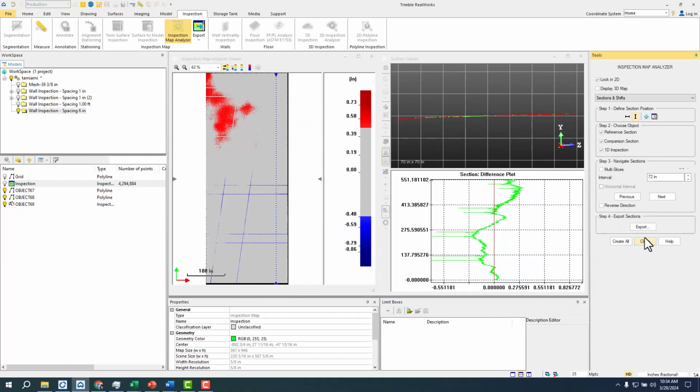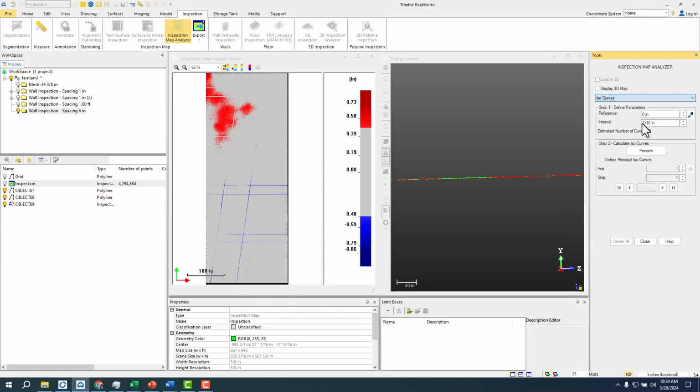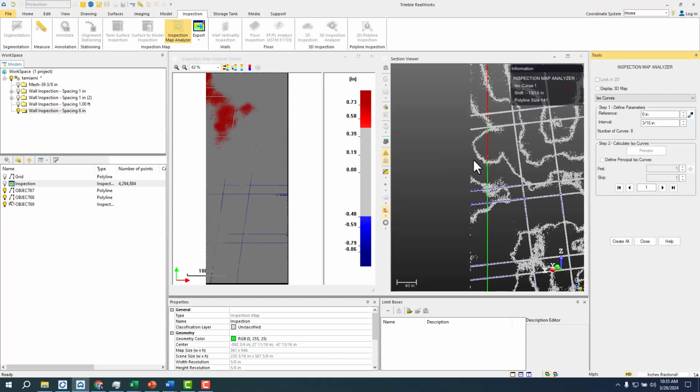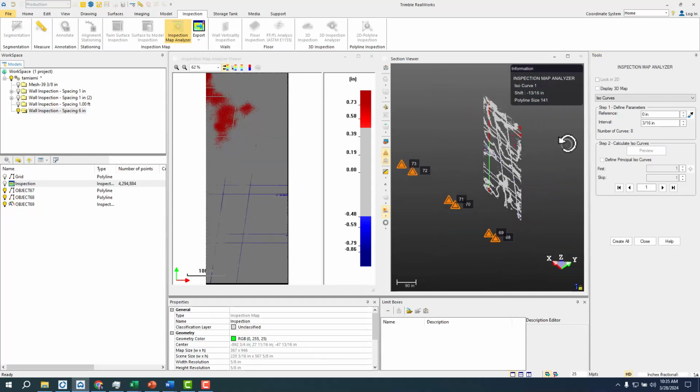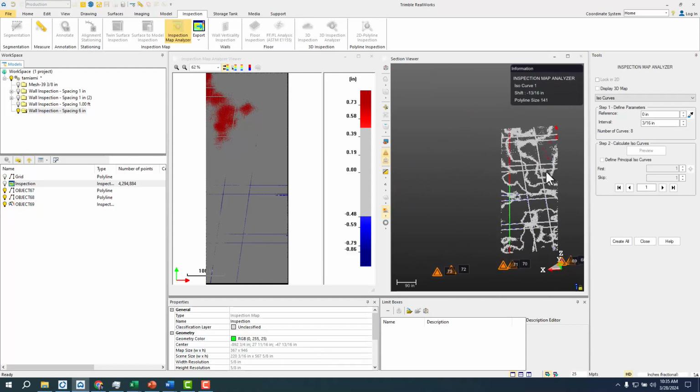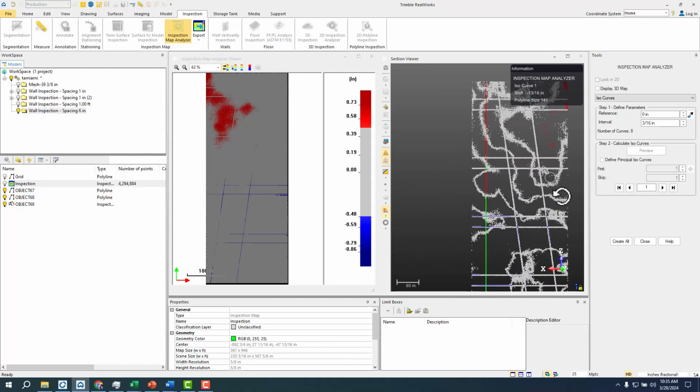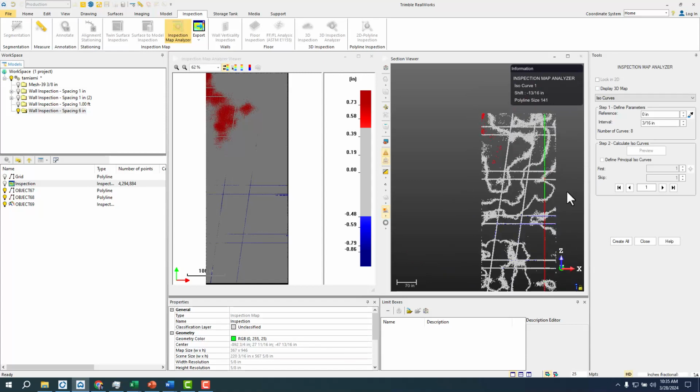And the other thing I can do, rather than just doing the vertical wall analysis, is do a contouring map, which can also be pretty nice because it's a little bit easier to interpret what the deliverable is there. Those section cuts are going to give me very precise differencing. Contouring will as well too, but this is sometimes a little bit easier to read just because people are a little more familiar with what that looks like for a contour.